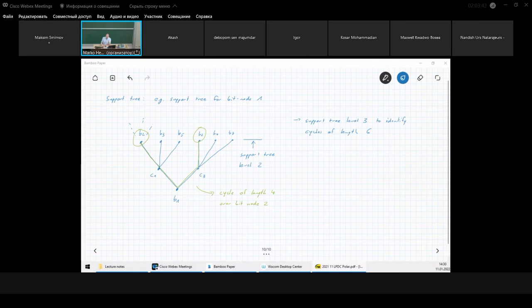So if we look at our Tanner diagram, we could have cycles of length 4, cycles of length 6, maybe also cycles of length 8. So we can have many different cycles, but the ones that will limit my bit error performance will be the small cycles. So we would like to get parity check matrices that result in Tanner graphs avoiding the small cycles.